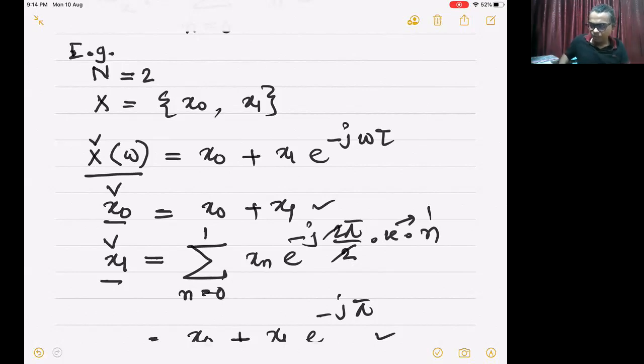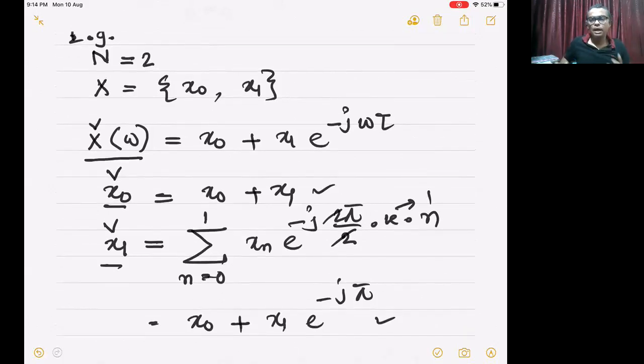Similarly here, this x check omega is what I should know. From Fourier transform theory, I know that I need to know x check omega in order to reconstruct x. But here, because it's a discrete signal, there are only these finitely many exponential functions which are present in the discrete time Fourier transform. Therefore, I can afford to know x check omega only at finitely many omegas. And at what omegas should we know them?